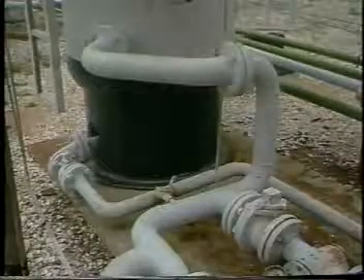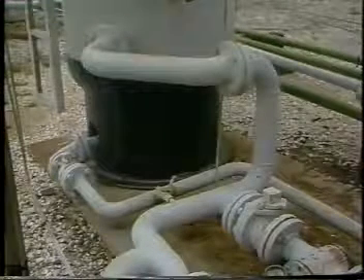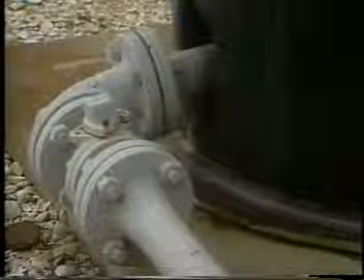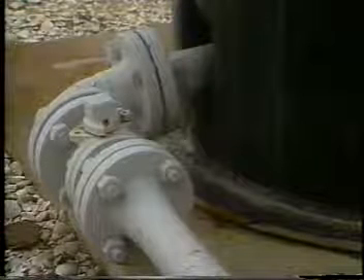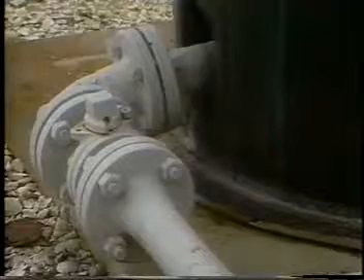Horizontal separators are not as efficient as vertical separators in the handling of produced solids. The liquid dump of a vertical separator can be placed at the center of the bottom head, so that solids will not build up in the separator. Or a drain could be placed at this location, so that the sand and clay could be removed periodically, while clean liquid leaves the vessel at a slightly higher elevation.